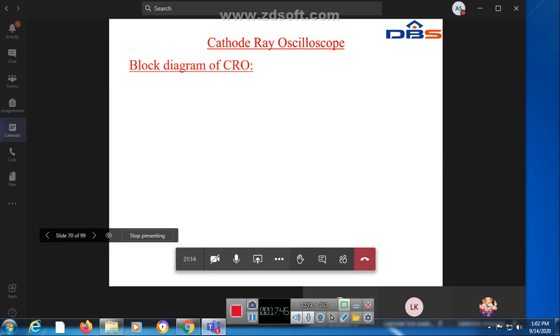Up to now we have been discussing measurement. To do that measurement you use an instrument, and what is essential for the instrument? When an instrument is working, three torques will compulsorily be acting: the deflecting torque, controlling torque, and damping torque. How these three torques are produced we discussed previously, and also the types of meters: PMMC, moving iron type, as well as the electrodynamometer. We also saw what an ammeter and a voltmeter are, and how to extend the range of an ammeter and of a voltmeter. These are discussed up to now.